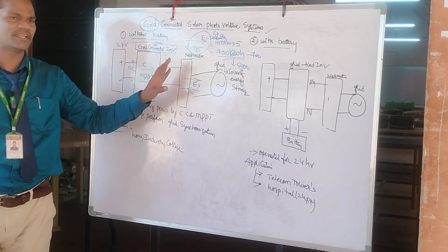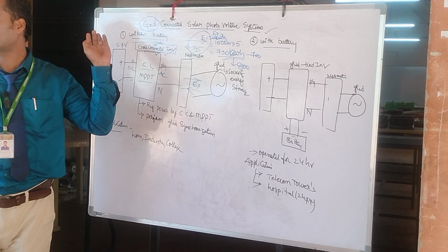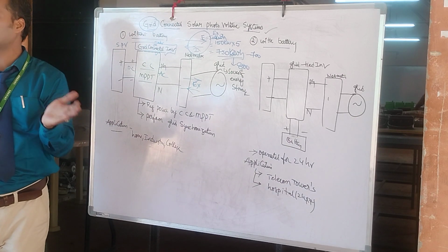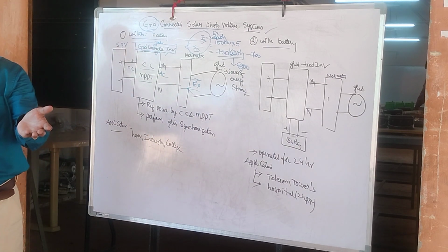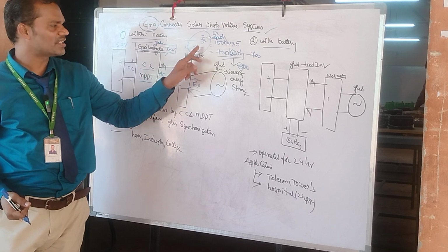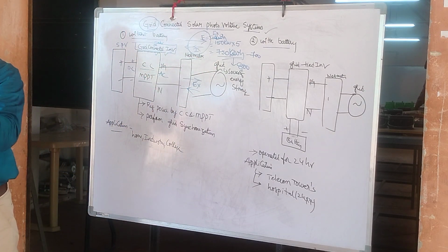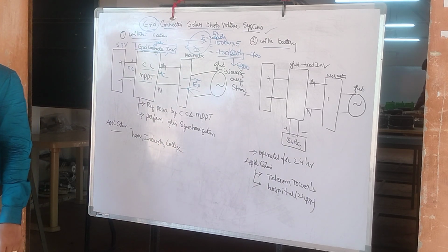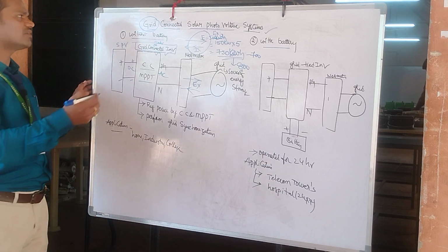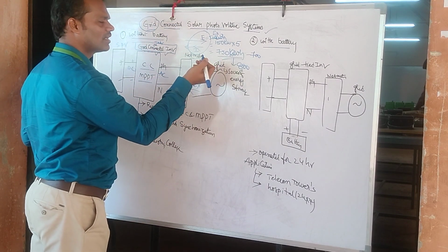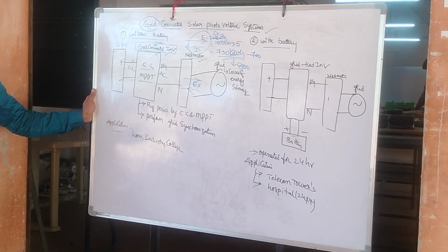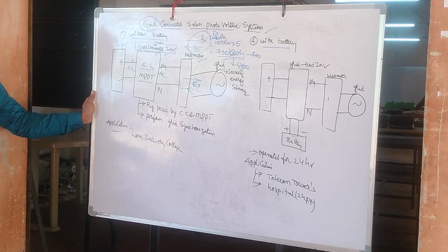This net meter will calculate how many units you have exported in 30 days and how many units you have imported in 30 days, so it makes the difference, import minus export. If you have exported more, then you will get the export in positive value, and they will pay you for the units exported at 5 rupees each. Automatically you get the revenue. That is why this meter is called a net meter. It calculates the number of exported units and imported units, and whichever is greater, it gives the data on who has to pay the bill. It's like a data logger.